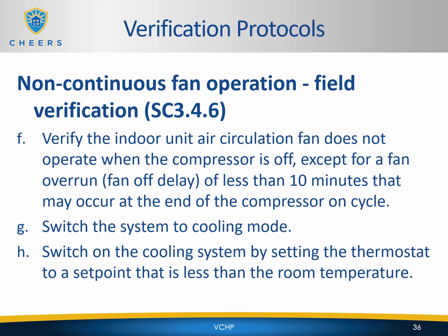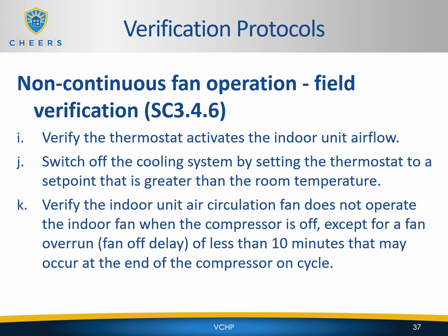Switch the system to cooling mode, and then switch on the cooling system by setting the thermostat to a set point that is less than the room temperature. Verify that the thermostat activates the indoor unit airflow, and then switch off the cooling system by setting the thermostat to a set point that is greater than the room temperature. Again, verify the indoor unit air circulation fan does not operate when the compressor is off, except for a fan overrun of less than 10 minutes that may occur at the end of the compressor on cycle.